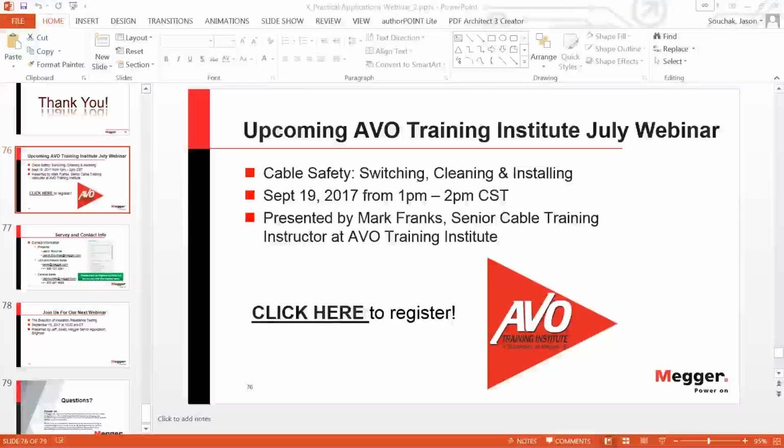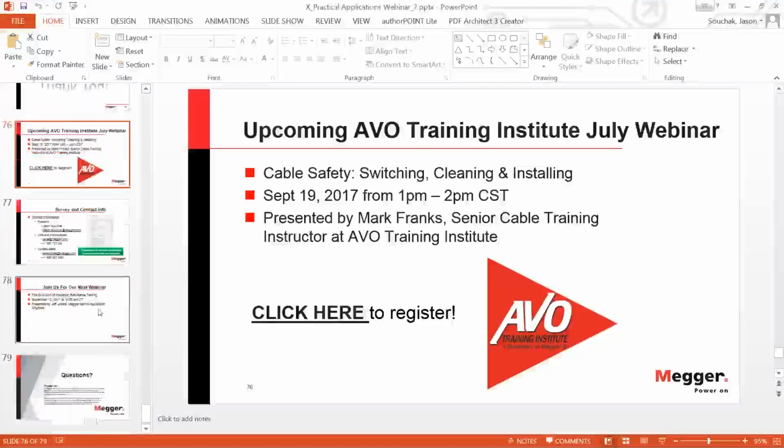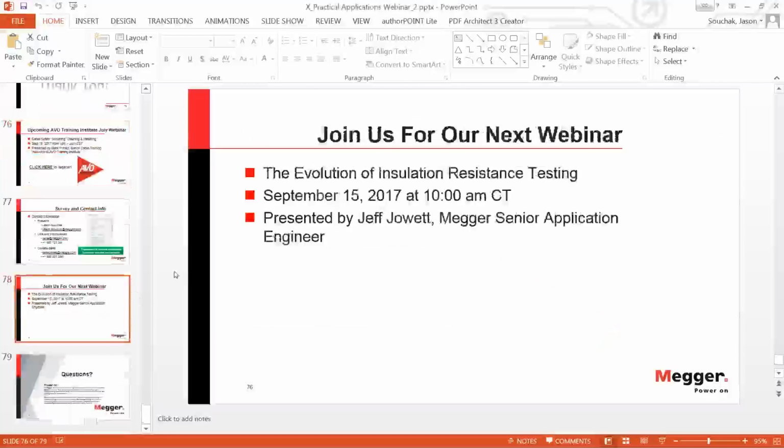The only other thing is, when you have a good tan delta reading, or let's say a tan delta reading that's within the norm, it means really, I hate to say, the cable is a good or bad cable, because it only tells you that the dielectric aging condition of that insulation is still very, very tolerable, very okay. That doesn't mean you could not have one spot in there, like Jason was showing there. You might have one bad water tree and that's going to blow, right?